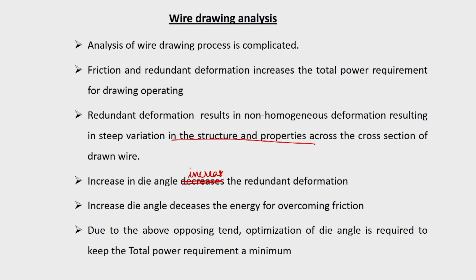So, for the draw stress in wire drawing, you have to calculate the strain for the wire drawing operation, that is epsilon w. It is based on the initial and final length, because you are just extending the rod or wire. Due to that there is a reduction in the cross sectional area and an increase in the length, which we discussed initially in the fundamentals of metal working.